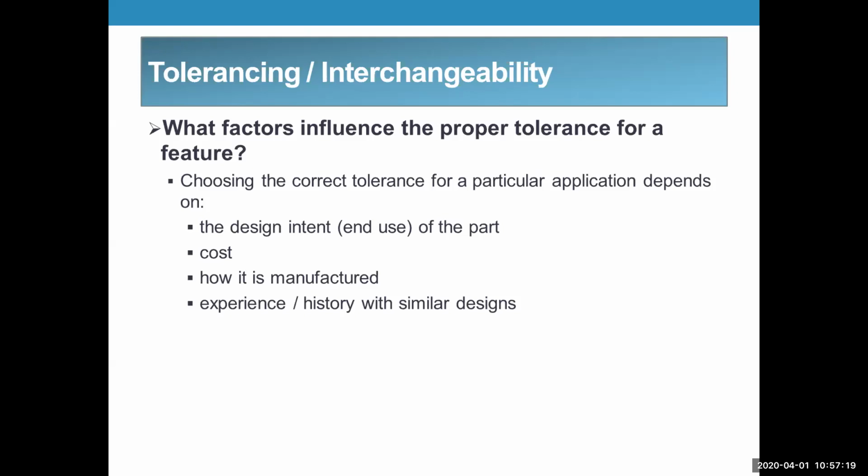But anyway, so if you know from experience, let's say you've seen other designs where you can allow the slot that the trigger pivots in to have a fairly loose tolerance and have it still function properly. Then you know that when you go to manufacturer B, you can probably use some similar types of tolerances and still be okay.